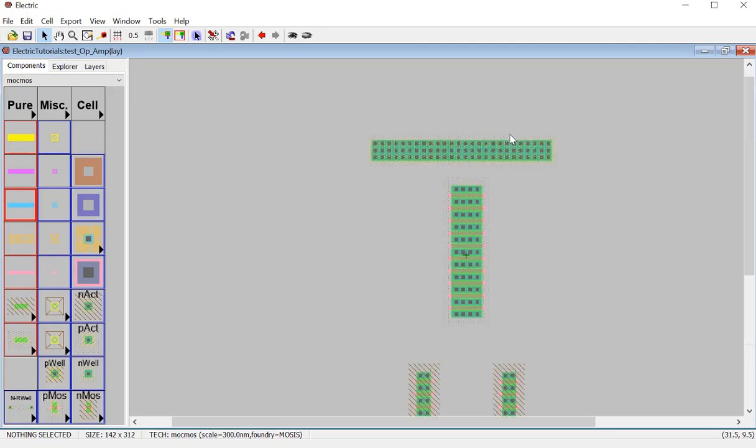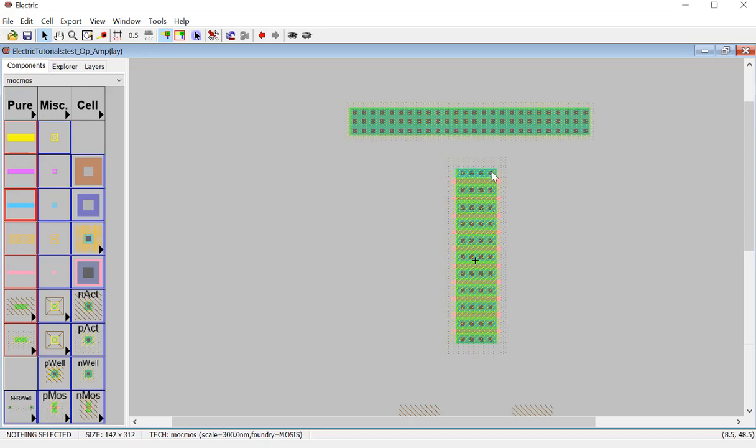And so now it's time to make all these fingers. So the metal 1, you can imagine that we are trying to connect the metal 1. So that's the first metal 1 to here, and then to here. We are skipping every P plus over here, and finally we short all the P plus together to make them the drain of the PMOS.